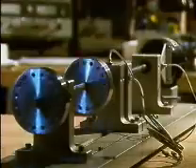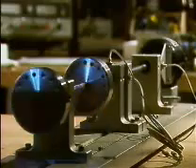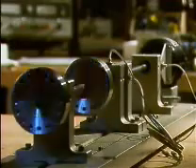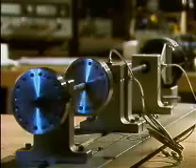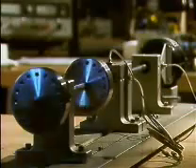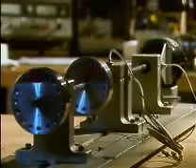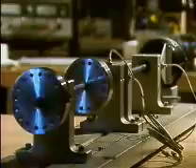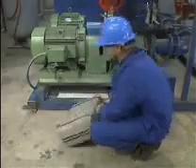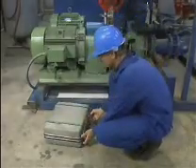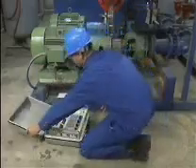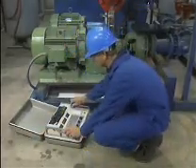During operation, the strobe light is pointed at a moving object, and the speed of the strobe is adjusted. As the speed of the strobe begins to match the speed of the object, the object will appear to slow down or stop. All vibration analyzers have specific instructions that should be followed to ensure that the collected data is accurate.